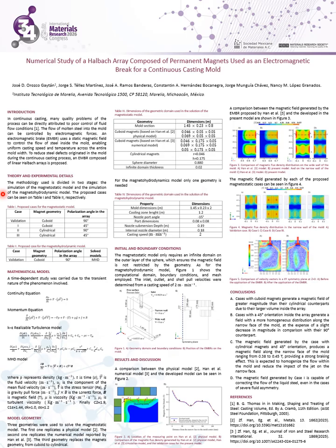As for the mathematical model, a time-dependent study was carried out due to the transient nature of the phenomena. We required the continuity equation and the momentum equation. As for the turbulence model, we selected the k-epsilon realizable model, and the MHD model for the solution of the magnetostatic cases.